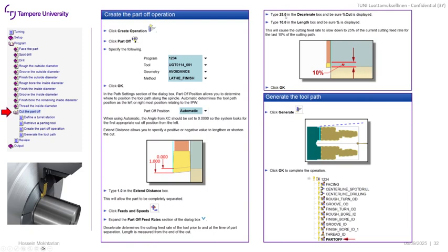So these two values of 25 and 10 are for decelerating in the specified millimeters. So 10 millimeters before reaching the center, since it's going to be a very small amount of the part available, and with the huge force and huge speed of the tool that we have, and we are cutting the part.